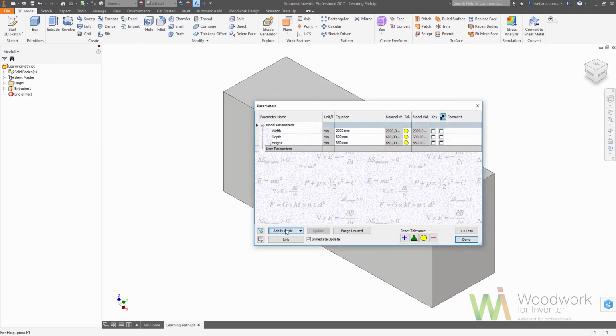Now we can enter the parameters like the body panel thickness, facade panel thickness, and internal panel thickness. Those parameters can be changed in the future if needed. So it's necessary to have an underline if your parameters have multiple words. So if there is more than 2 words, then you need to use underline in between those words. Okay, when we have a parameter list, we can close this window.